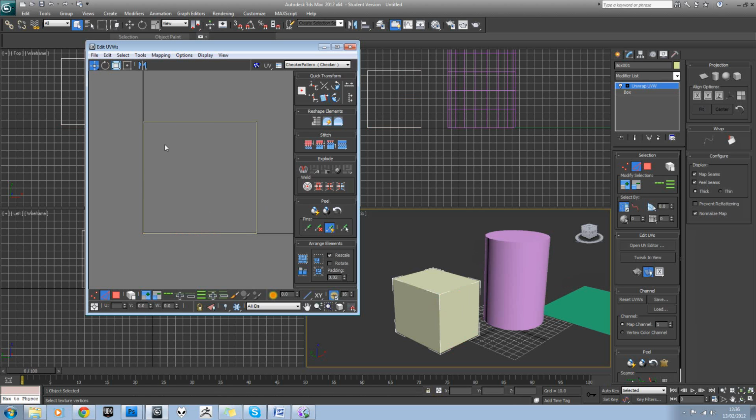Okay, so you are initially pretty much always presented with this kind of confusing original layout. So there's a couple of basic tools just to get you started. If you go over to the Mapping tab, you see you have Flatten Mapping, Normal Mapping and Unfold. And then on the right over here in your toolbar you have your standard UVW tools, Planar Map, Cylindrical Map, Sphere and Box.